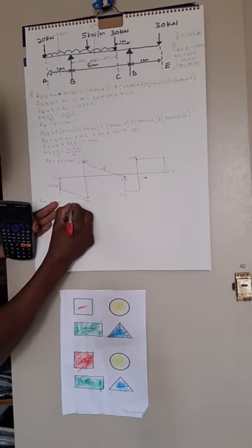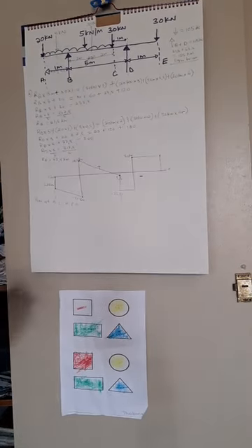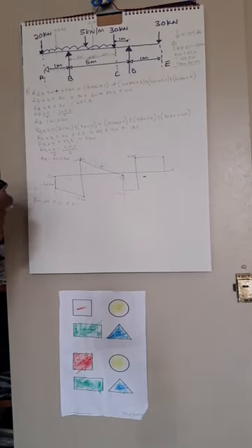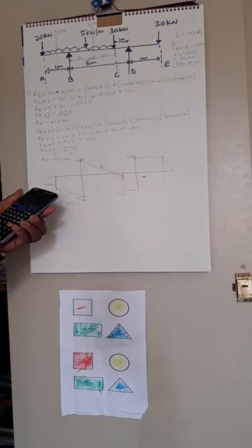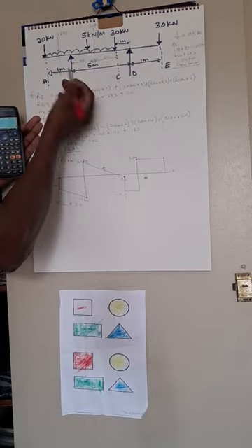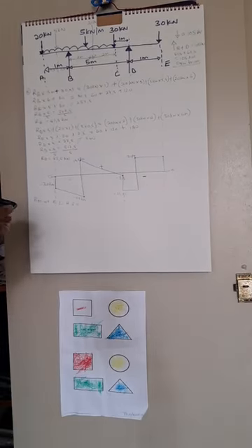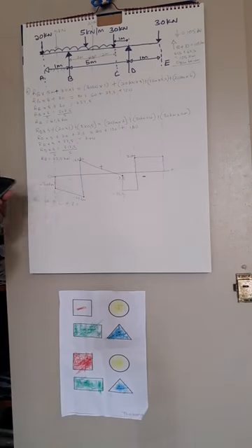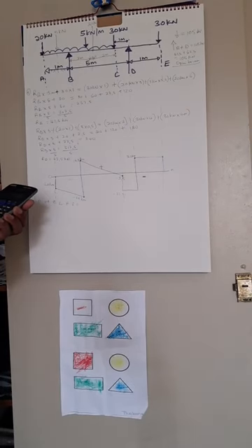So we already know that bending moments at B, we can calculate from the left hand side. But in the exam, you can choose any side which you want. So bending moments at B from the left hand side, we have a minus 20 times the distance from here to here, which is minus 20 times 1, plus minus 5 times 0.5.